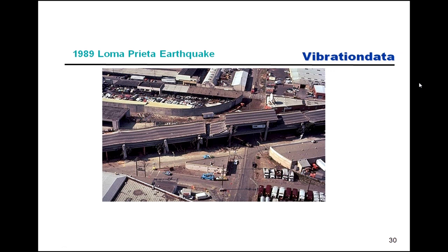But the consequence of that is some of these areas we would characterize as being weak soil with a high moisture content. And if you think about the ground as being porous, during an earthquake there are different frictional effects occurring with these pores. And the moisture of the water is drawn up through the pores, and that can result in an unstable foundation. And that can even lead, in extreme cases, to something called soil liquefaction.